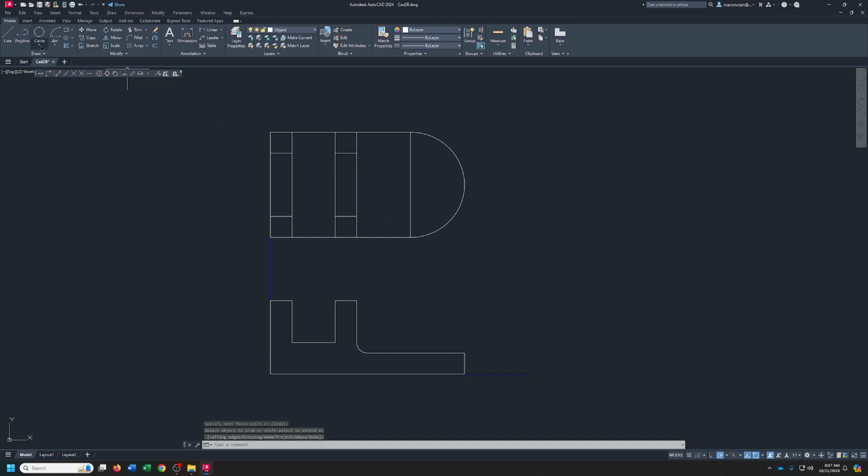We need one circle. It's going to be diameter of 1. So we'll go ahead and pick the center of this, diameter of 1. Now, grab this, change it here to center. Okay? While it's still highlighted, click on rotate, pick the center of the circle. Then right-click again, pick copy, and go straight up and click. That will give you your center line for that hole.